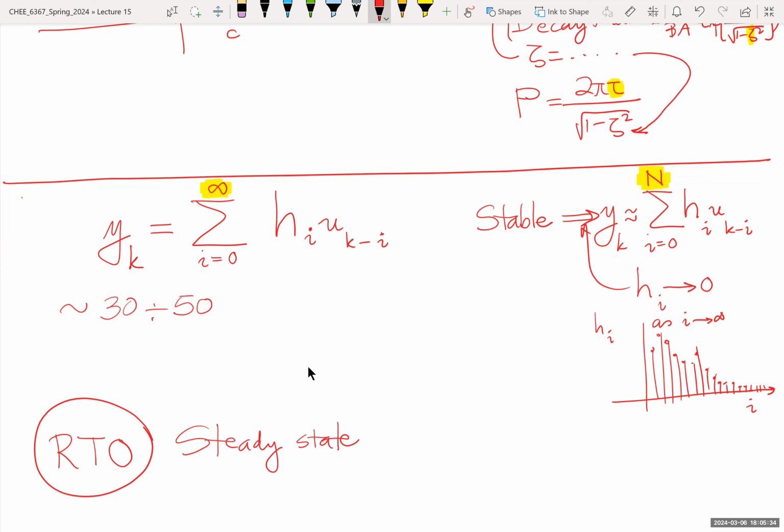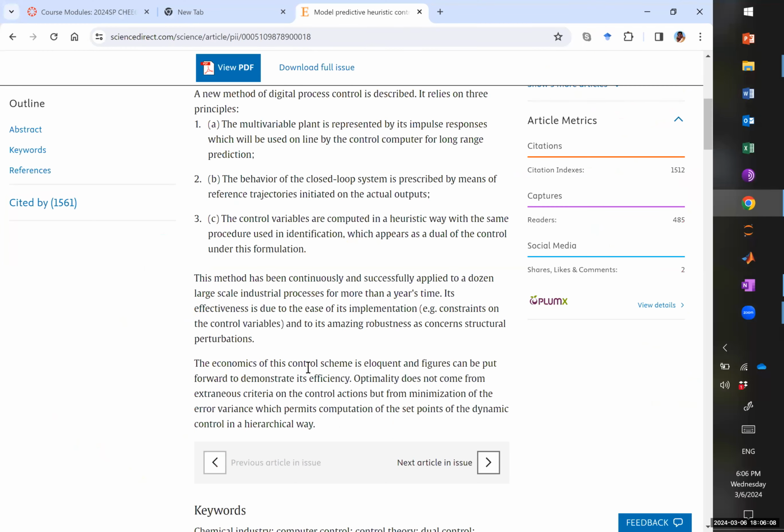And over steady state, you have actually full nonlinear effects of inputs and outputs. And that's why you need a process simulator. And then you use your process simulator to do optimization and find the optimal settings over an entire shift. Now, during that shift of 8 or 12 hours, things fluctuate, and your controller should select optimal settings for the manipulated variables. These people thought about that long and hard, and they reasoned as follows.